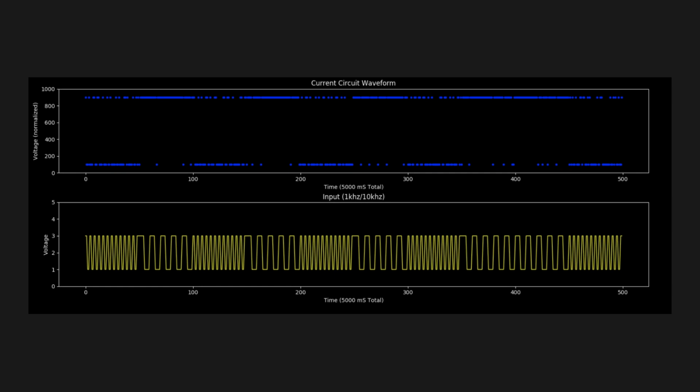We posit that using a simulated op-amp relieves part of the setup from extraneous environmental noise, including signal crosstalk and temperature variations. The top plot shows the output voltage from the simulated op-amp and is vertically aligned with the bottom plot, which shows the order of tonal input. You can see that the evolved circuit more effectively classifies the 1 kHz over the 10 kHz tone.